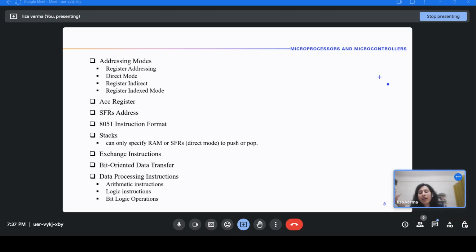It's difficult, but you'll have to remember, since the stack in 8051 is in your internal memory, it is 8-bit, and the stack pointer is an 8-bit register only, not 16-bit as in 8085. It is going to increment after the push. The logic is the same, last in first out, but the value of the stack pointer will be incremented, not decremented.